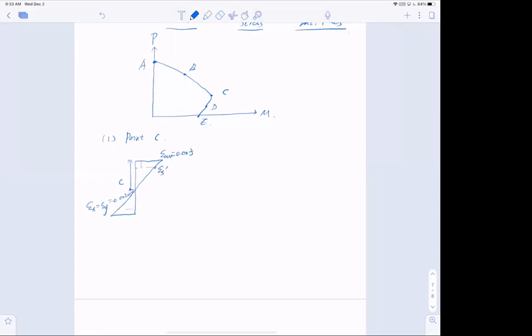And the distance between the top fiber and the compressive steel is ds prime. All right, and knowing that the depth of the bar is d here. Okay, so these are the strain distribution. I can start computing to get my compressive zone size.